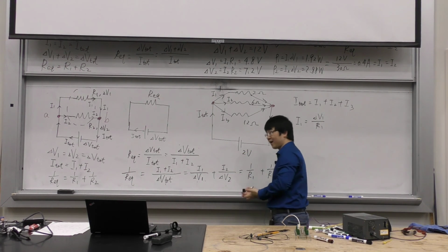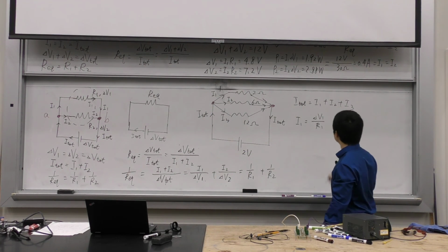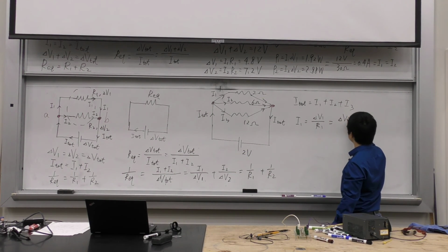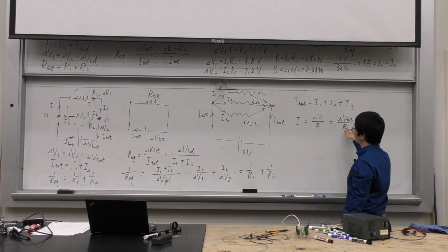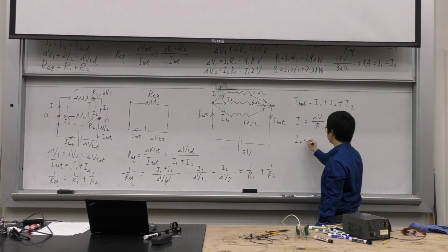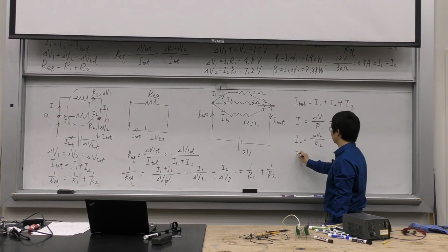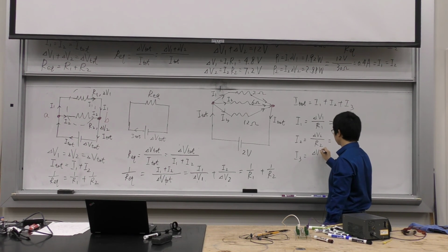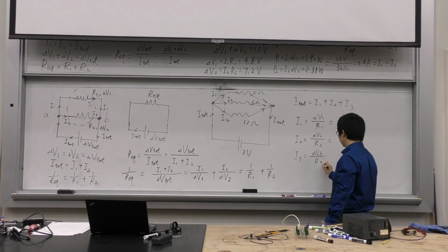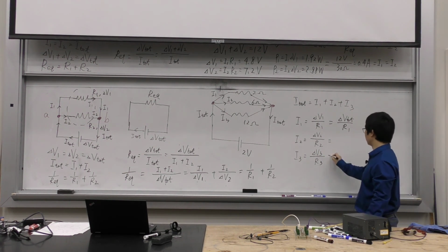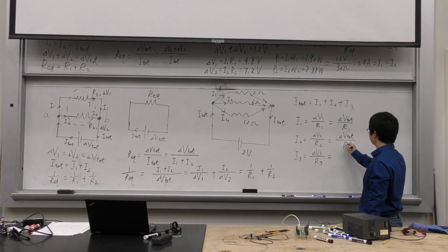So they will all get 2 volts from the battery, so this is just going to be equal to V total. Now you have these 2 numbers, plug them in, and you find I1. Then you do the same thing for I2 and for I3. At the end you add them together, because the total current is the sum of all these currents if they're in parallel.